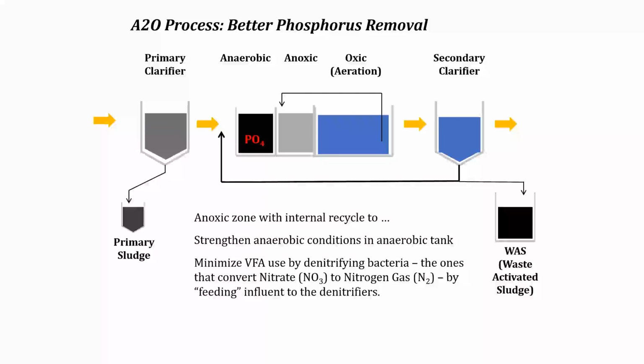Release the phosphorus, 3-to-1 ratio, what's coming in here versus what's going out here. It's a 3-to-1 ratio. The soluble phosphorus and the energized organisms basically pass through the anoxic zone with little to no change. We still have the phosphorus in solution. The energized PAOs are still there.